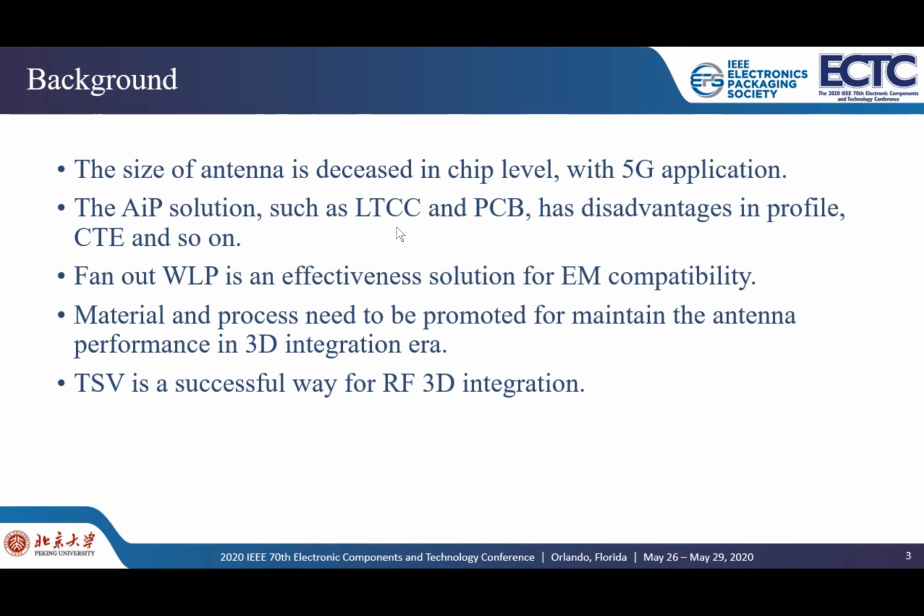As for EM problem, the fan-out wafer level package is an effective solution, but it will consume more area. For 3D integration with logic IC, the material and the process of radio frequency IC need to be changed to solve the integration problems. The TSV and the process based on the silicon substrate is a good solution for this.